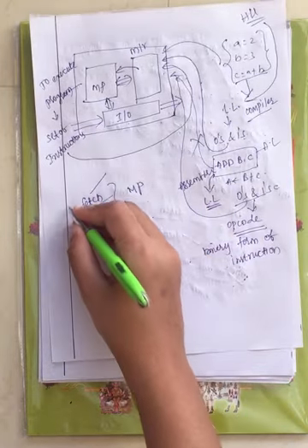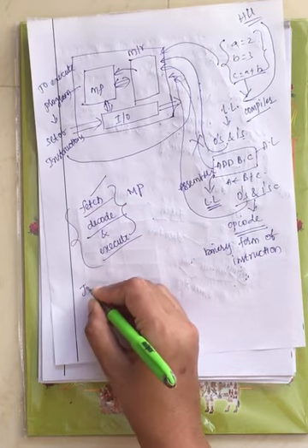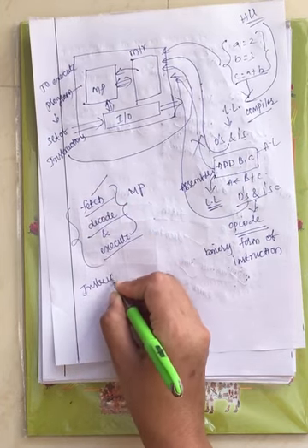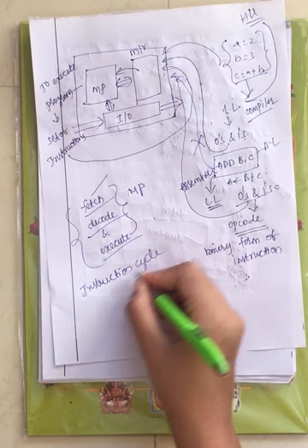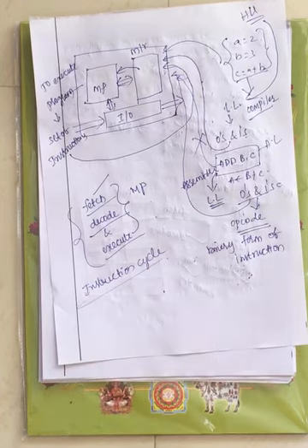This is how the processor works, and these 3 steps together, fetching, decoding and executing, we call an instruction cycle, right? All these 3 steps are done for a single instruction. For a single instruction, first we take it, decode it, and then we execute it, right?